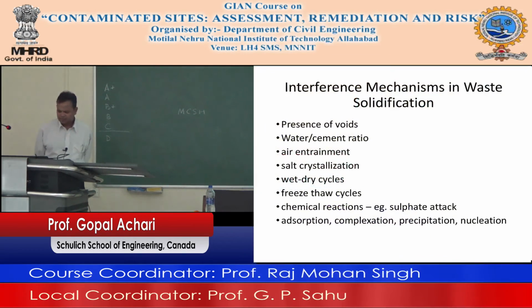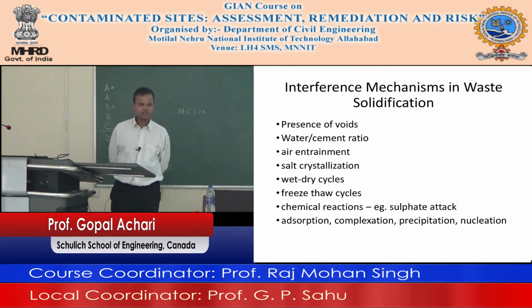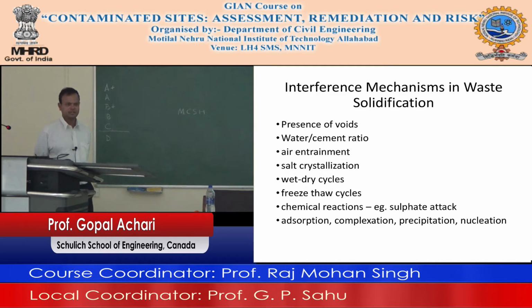So these are some of the interference mechanisms. Presence of voids, water-cement ratio. If you have too much water, the cement will remain a soup and will never actually set. Air entrainment. I mean, half of you are civil engineers, I think most of you, so you recall what air entrainment is.